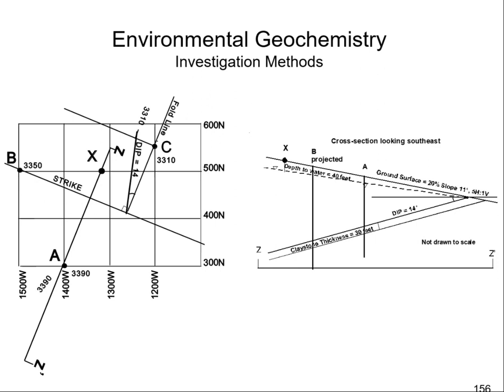The slope is sloping down to the south-southwest, so I did a cross-section to the south-southwest, and that happens to be perpendicular to strike, which we are not solving for strike and dip here, and it's given to you. If that's not part of what they want you to be working with, then they will generally make things a little bit easier, like making this direction perpendicular to strike. It also happens to go through the location that borehole A is located in.